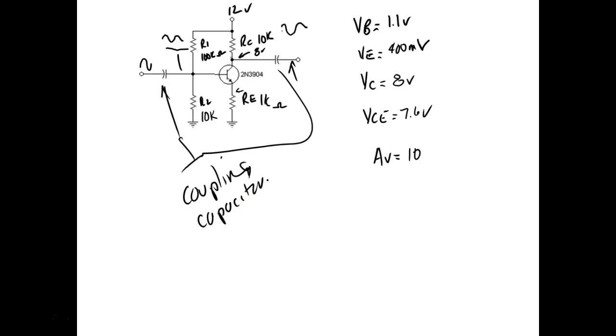Now, odds are, when you get out here and look at these things, you're not going to have to calculate them, hopefully. These voltages are going to be given to you. But now you understand where they come from, right? And we know this is not a real good amplifier. Why? Because I got 12 volts right here, and I'm setting this sucker at 8, right? You understand? Where would we like DC to be at? We'd like it to be at 6.